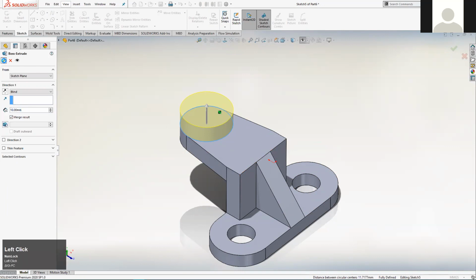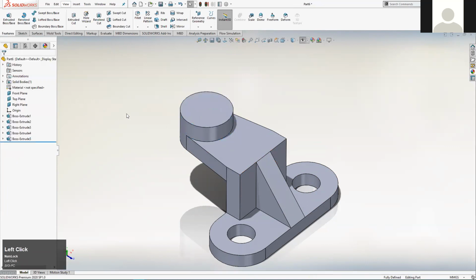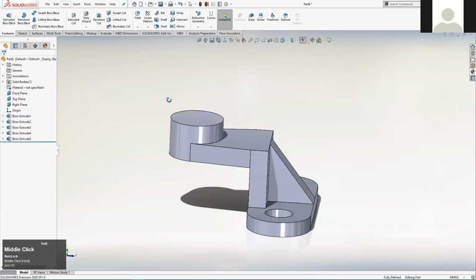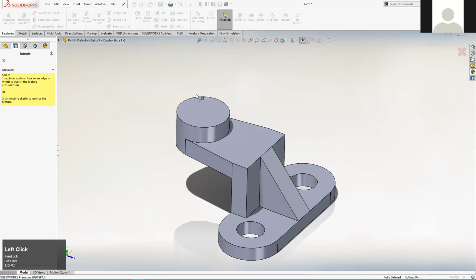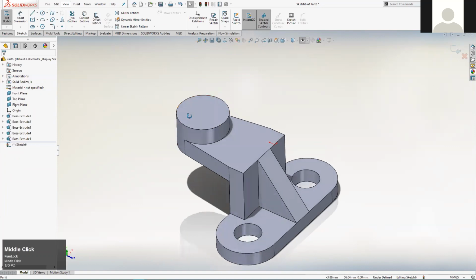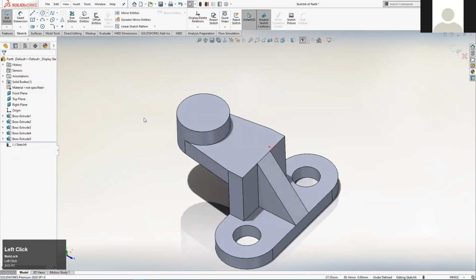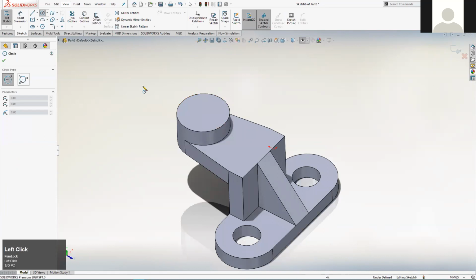So that's good. So we've got one left, which is the extruded cut, which there's nothing particularly advanced about this. So extruded cut, create the sketch on that top surface. So click on there, create a center point rectangle. So let's see if we can get this one auto referencing this circular edge.